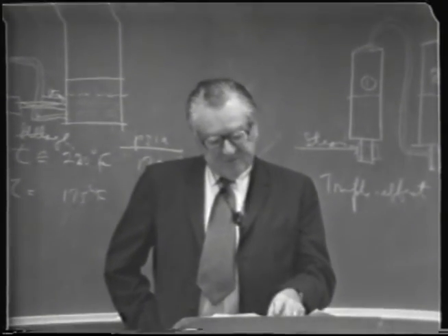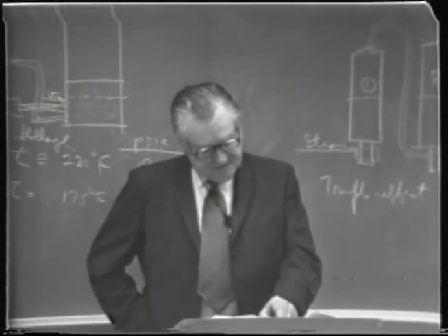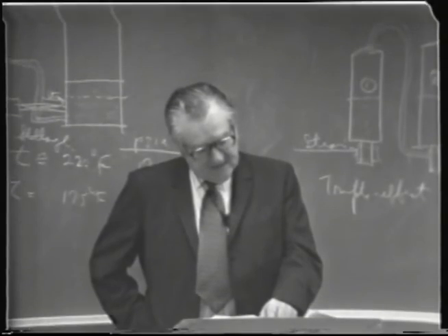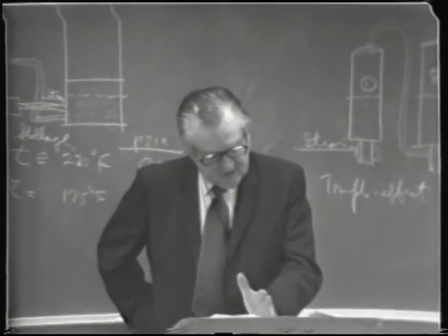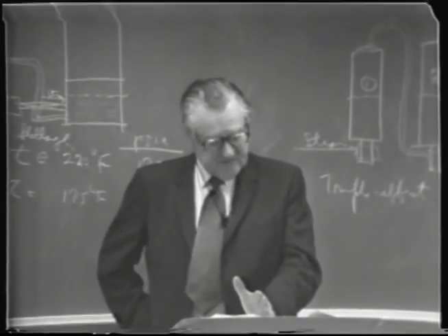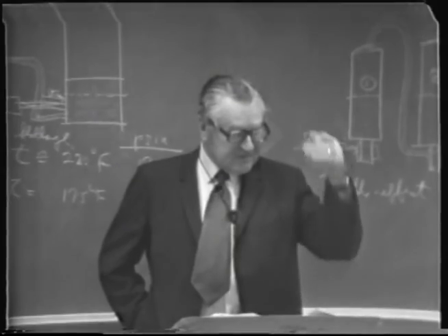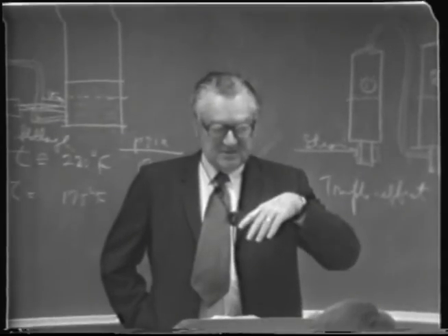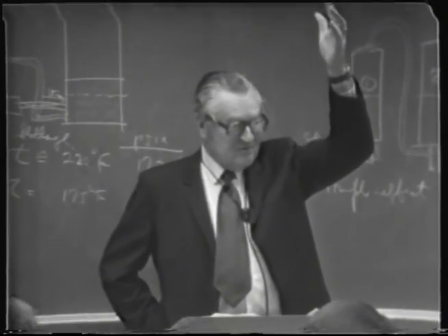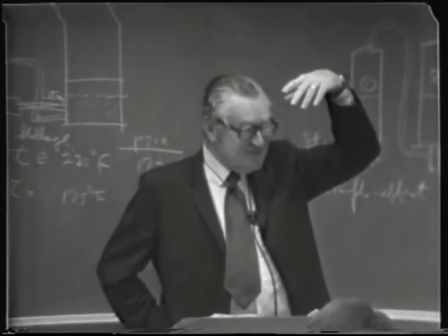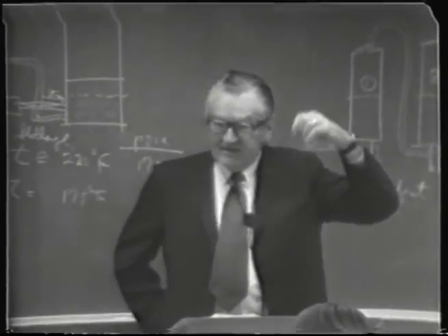Now that sort of corresponds in principle to the purifying column, where low wines is run in, but the alcohol content on the trays on the column, called an extractive column, are kept much lower by actually introducing boiling water up at the top level and diluting it. So you dilute it down so far that not only the heads are more volatile, but the high boilers are also more volatile, and they come off in the heads also. Fusel oil and the fatty acids and fatty acid esters and so forth.